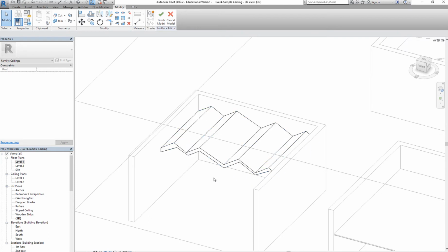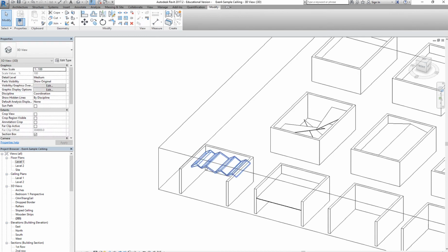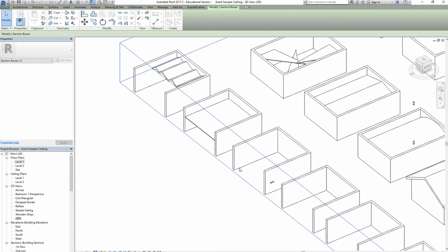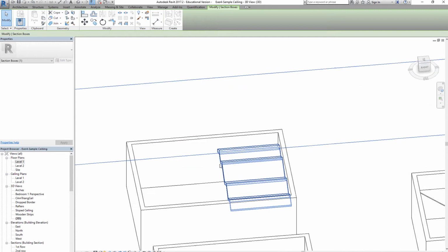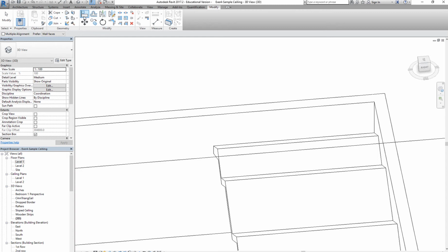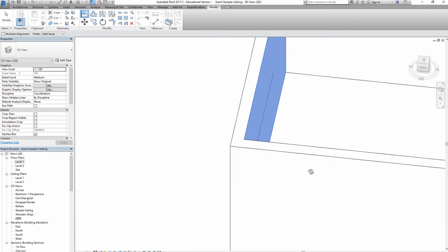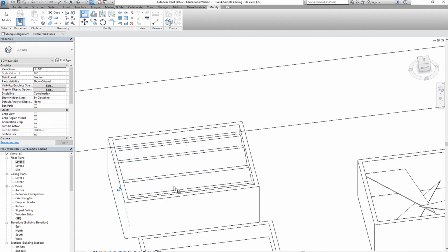Now, like I said, if I check this to finish the extrusion, I can go here and let me just move this. If I want to, I can close this up by saying align. Okay, click on the align tool or type AL. Select the surface you want it to align to. So in this case, the interior surface of the room. And what do you want to align? This guy here. And it gets aligned.